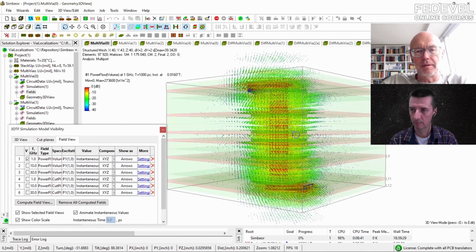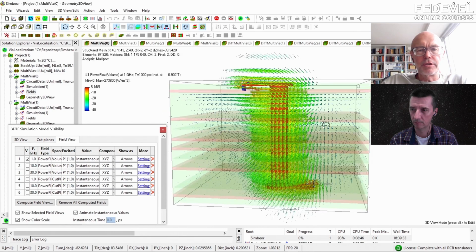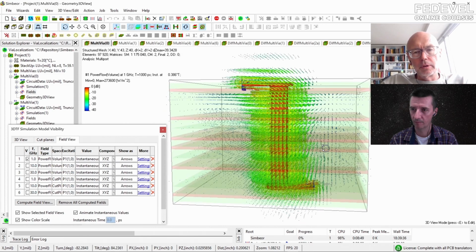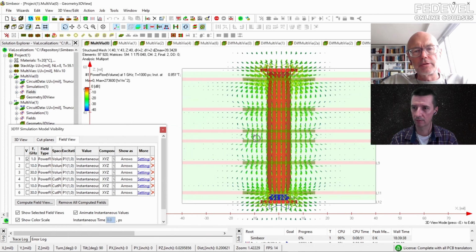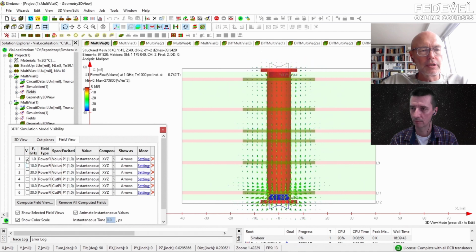Essentially, it shows where the energy of your signal propagates. So it's not in the currents, it's energy in fields. Exactly, it's in the spaces. So your signal travels in the spaces, and in this case, it travels through a multi-layer board. This is exactly the stack-up as you had it, and you can see that some of this energy gets through, but some of it is spreading.